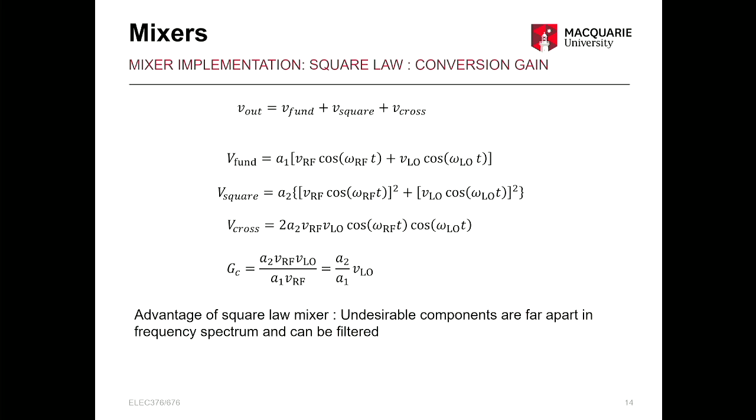So we don't really care about the frequency of the local oscillator, because that is in our control. We can change it. There is no issue of noise because we are generating it locally, so the amplitude can be as high as we want. So that's not an issue. The issue is the RF signal. RF has to be picked up by the antenna, which is in the air, propagating. You need to pick it up using the antenna, and then use it with the local oscillator to produce the IF frequency. So that is why the conversion gain doesn't have the ratio of LO in it.